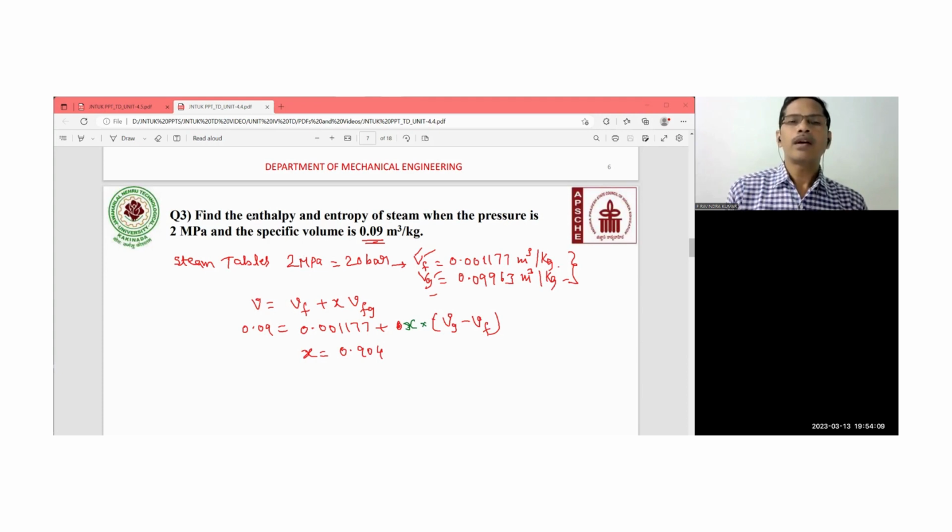Then you have to find the enthalpy and entropy. Enthalpy H is equal to Hf plus x into Hfg.